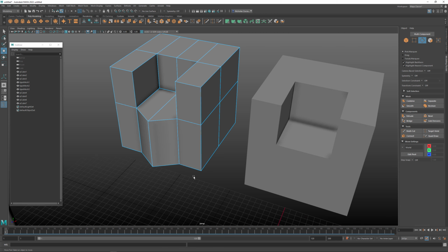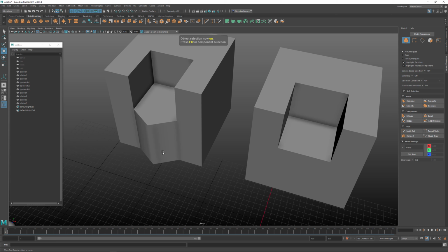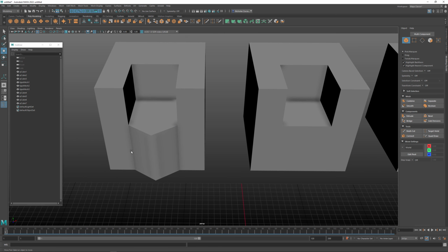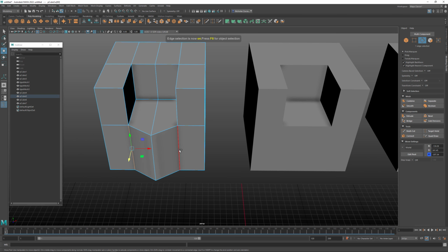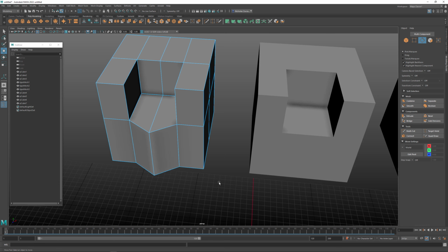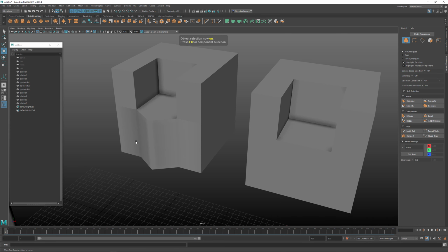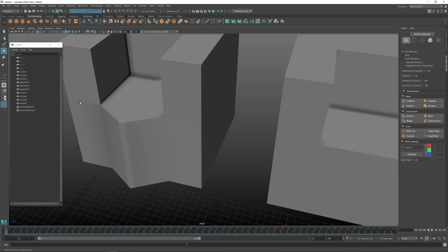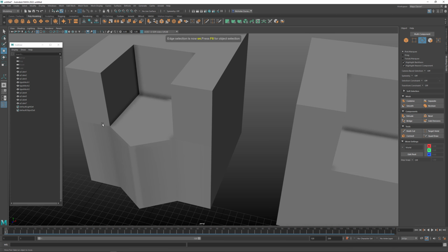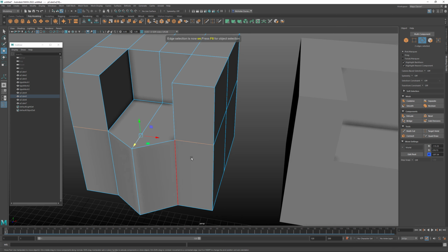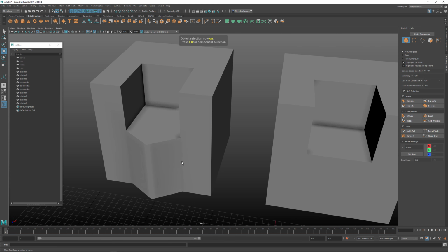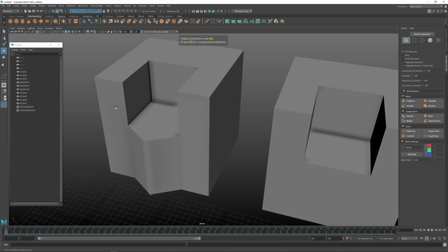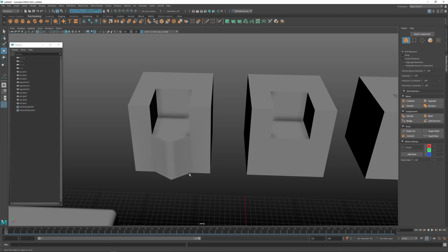You can see now we're starting to get some smoothing across there, and if I wouldn't want hard edges on these edges here, I can select it and Shift right click and soften the edge here, and you can see how we're starting to build some nice shading across here, but you can still see it's still hard in through here. So if we select this edge and this edge, Shift right click and say Soften Edge like this, it'll shade smoothly across this entire face. So maybe that's what we want.